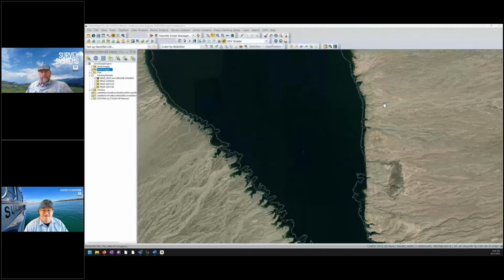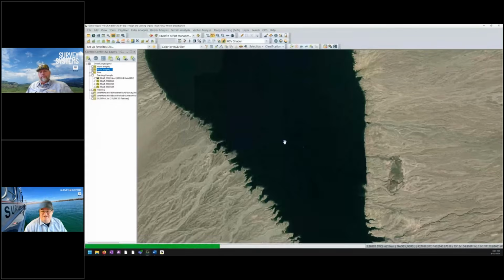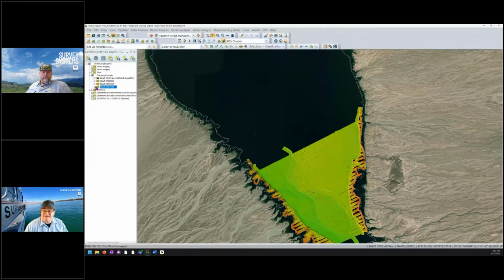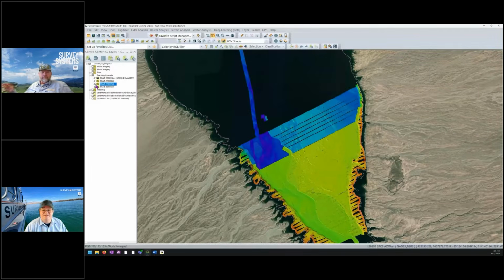The next step that I used in Global Mapper was keeping track of our dailies. Every day as we brought data in, I would kick it out in a format just really quickly to bring into Global Mapper, so I could review what each day was looking like. I could check for any missing lines or any spots that we needed to get a little bit more detail in.